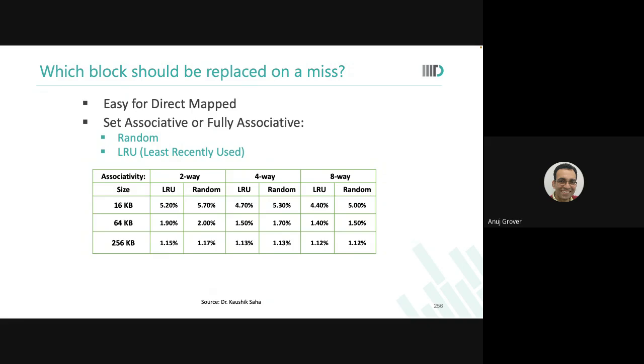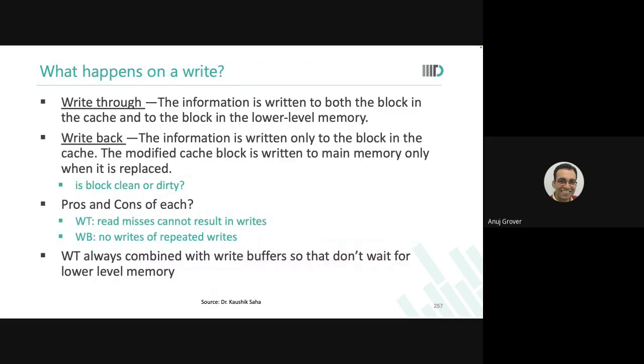So we also talked about write. In the last class, we said that write could happen in 2 ways. One is write through. Whatever I'm updating in the L1 cache will be updated in all the other hierarchy. Because of the inclusion property, everyone has that same data. Or I could be doing write back, where I will not update the higher hierarchy. I will simply put the valid bit as 1 or 0. Thus saying that the data in the higher level is invalid now.